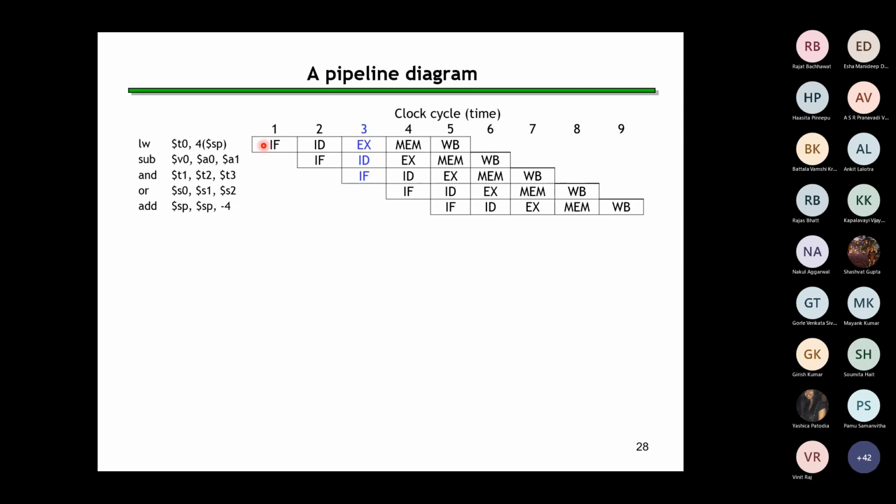And therefore, since my instruction is partitioned into different components and my hardware is also partitioned into different modules, I have overlap in time, but these modules are all different. They are active at the same instant of time. So this is where I'm getting maximum parallelism, and here you can say that the pipeline is full now, because every module in my hardware system is now busy.